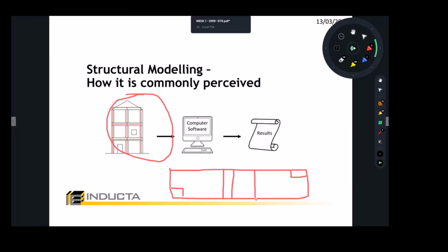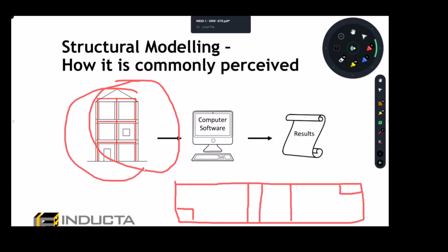Your concrete beams and columns will be engaged together in a way where they all act as portal frames. And I can tell you, such simulations cannot be done adequately by RCB. You're going to need to go back to Space Gass or SAP 2000, because it's going to be sticks, something like what you have here.